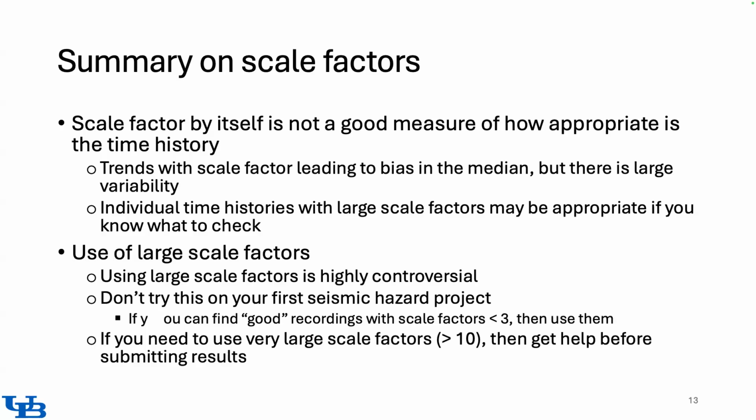So this is sort of a summary: the scaling factor is something that, if someone asks you to select time histories, is one thing you should be mindful of, but it shouldn't be the entire reason for how you select time series.